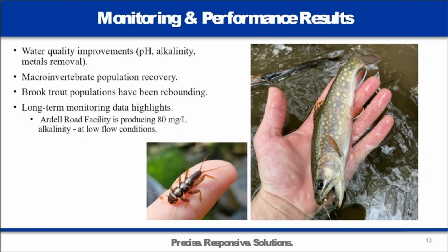And kind of the performance of it, so Ardell Road was built in 2001, and we now have almost 25 years of continuous operation of that. They were built with a 20-year expected lifetime of the compost. The compost will degrade over time. It rots, and that's actually what uses up your oxygen within it. There's enough limestone for approximately 80 years at the designed flow rate.